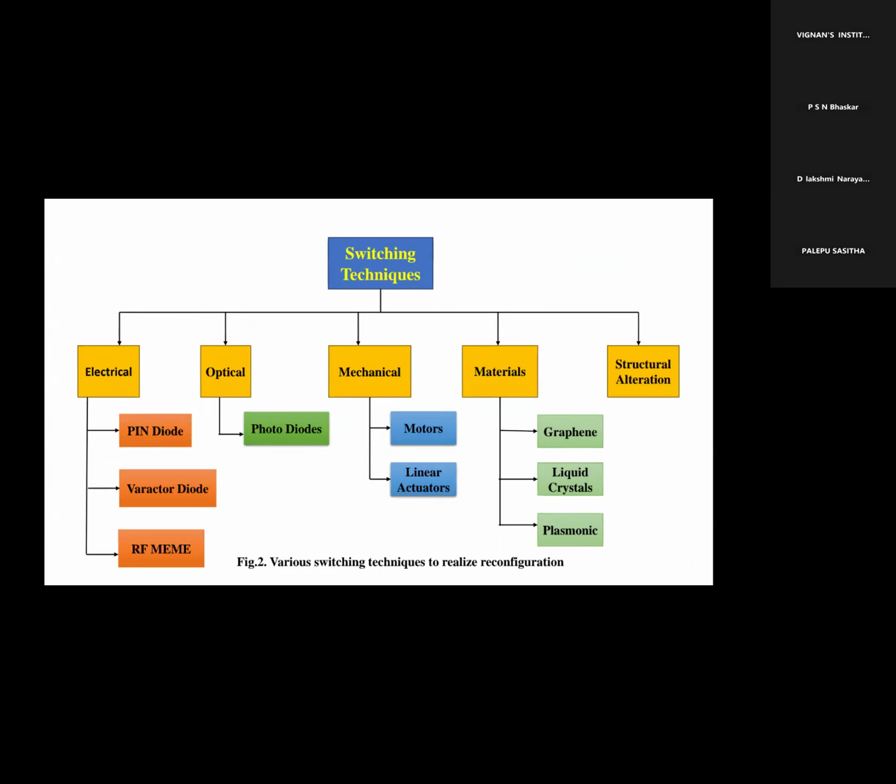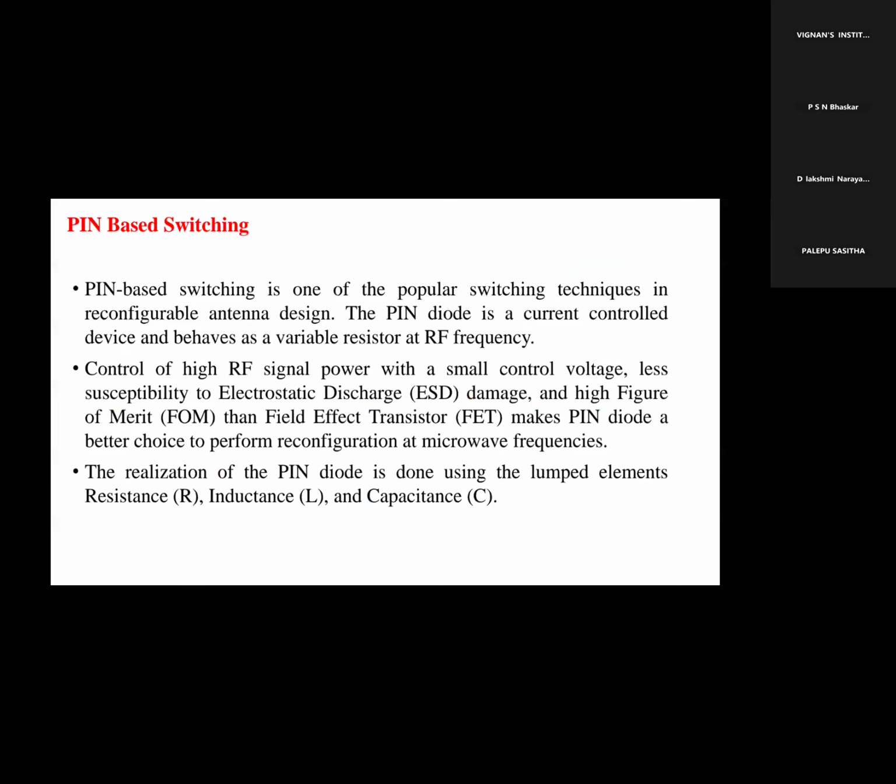Now we'll discuss PIN diode based switching. PIN diode switching is one of the popular switching techniques in reconfigurable antenna design. The PIN diode is a current controlled device and behaves as a variable resistor at RF frequencies. Control of high RF signal power with small control voltages, less susceptibility to electrostatic discharge damage, high frequency, and a higher figure of merit than the field effect transistor make the PIN diode a better choice to perform the reconfiguration at microwave frequencies.